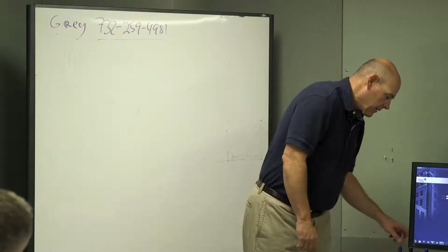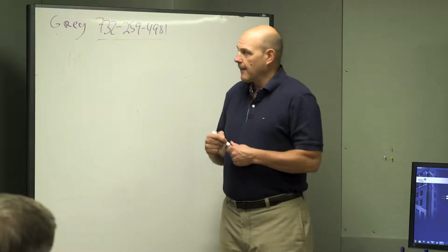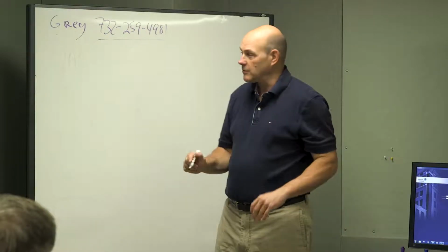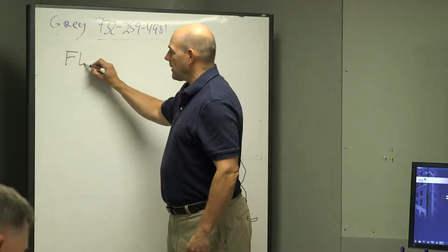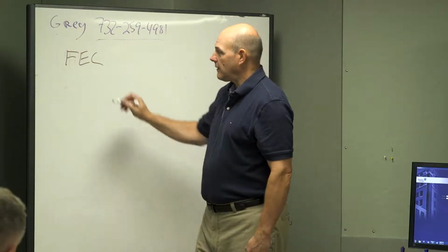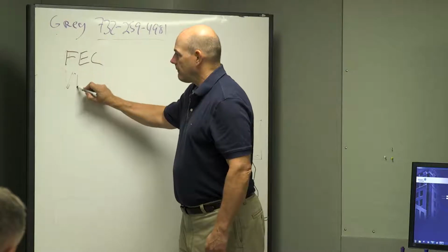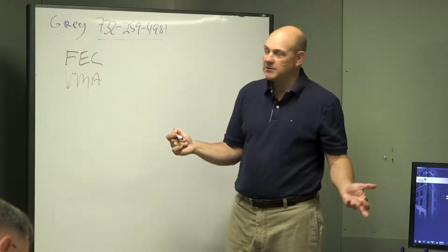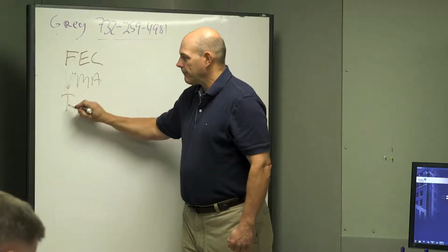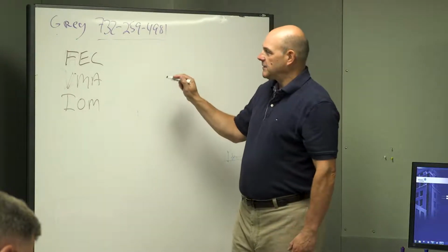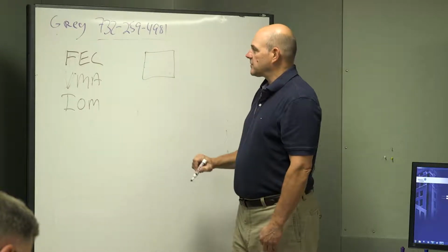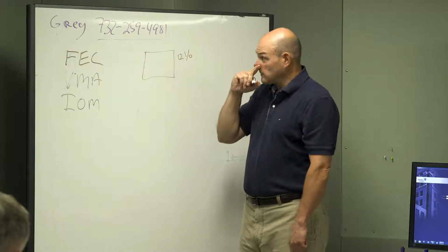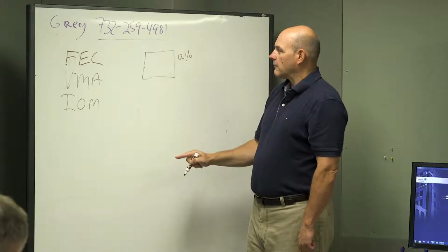Now what we're going to go through is, I'm going to change this. You saw how we had a network communication go to all, this is a mother controller, now we have baby controllers, which the baby controllers can be a FEC, right? A VMA, which we don't care about for the chiller plant, but that's what controls a VAV box, and an IOM. So a FEC comes in various ranges, but that thing has 12 I/O, input outputs, and we're going to go to what I/O means, right?